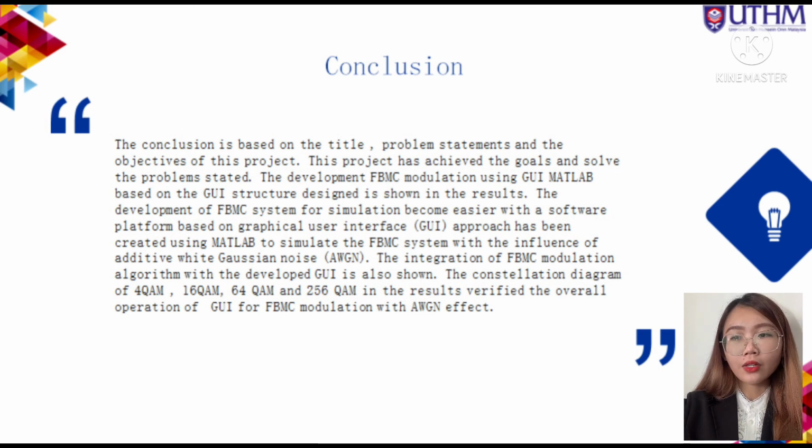The integration of the FBMC modulation algorithm with the developed GUI is also shown. The constellation diagrams of 4 QAM, 16 QAM, 64 QAM and 256 QAM in the result verified the overall operation of the GUI for FBMC modulation with AWGN effects.